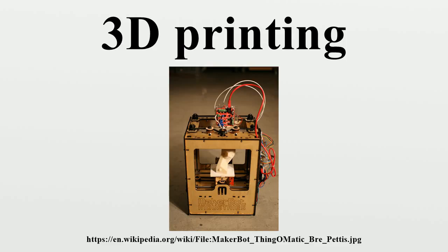Some additive manufacturing techniques are capable of using multiple materials in the course of constructing parts. These techniques are able to print in multiple colors and color combinations simultaneously, and would not necessarily require painting. Some printing techniques require internal supports to be built for overhanging features during construction.